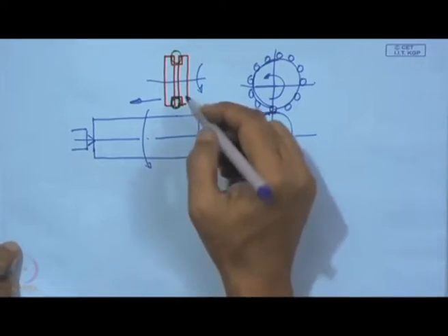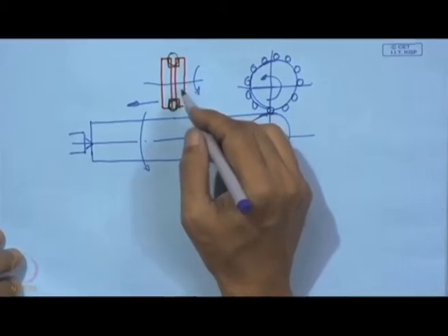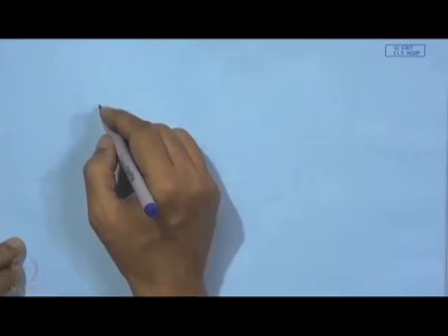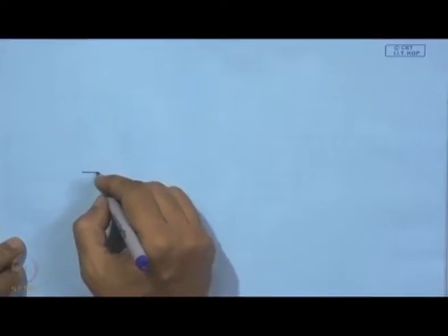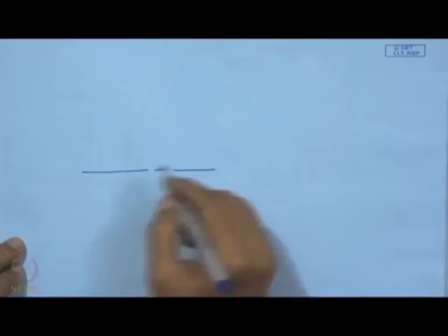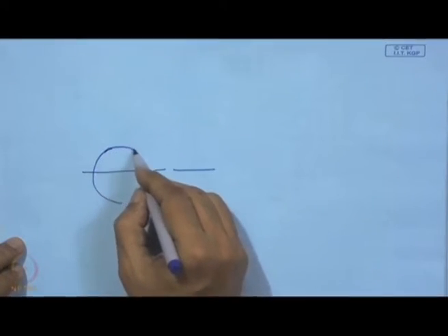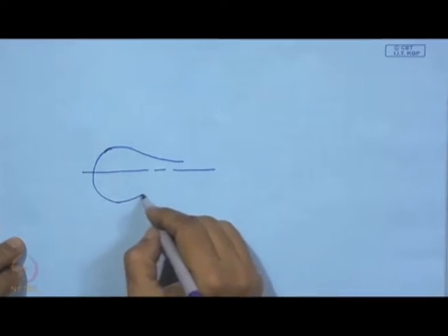So, this can be done in the grinding machine itself. Now, this ball burnishing can also be extended to improve the property of a contoured surface. Say for example, we have a contoured surface with a certain axis of symmetry, and this is going to be an axis.